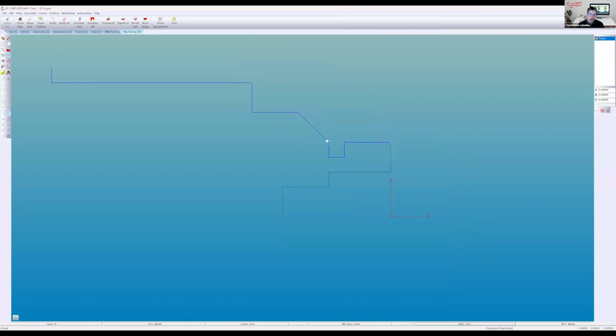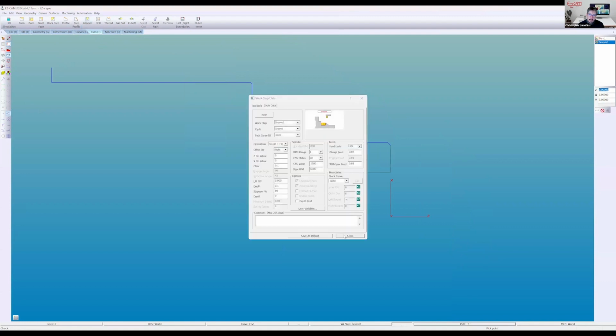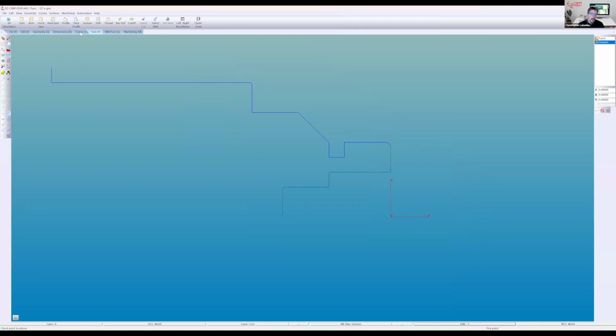That's for the solid models. So just a quick, we'll just add the groove here real quick. External. You have to create a curve. And here I'll use arc move and walk around the grooved area. Add that to our work step, curve number 2.